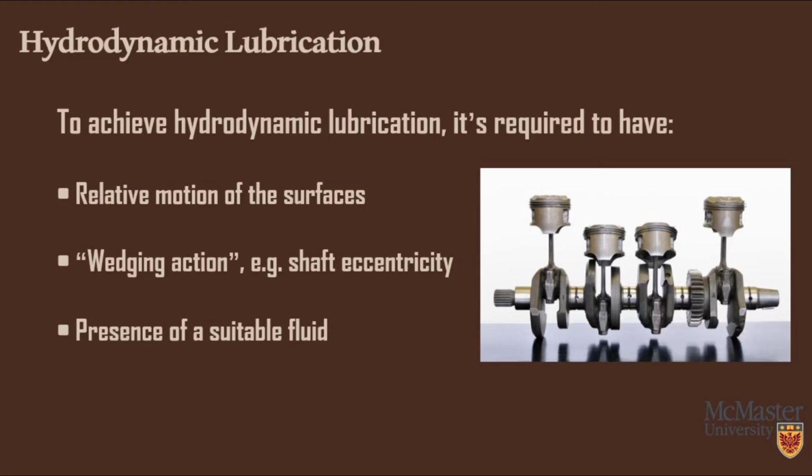The engine crankshaft only turns slowly when the crank is turning, and the load is small because there is no combustion load. Once an engine is started, combustion will greatly increase the bearing load, but the speed will increase enough to establish hydrodynamic lubrication.